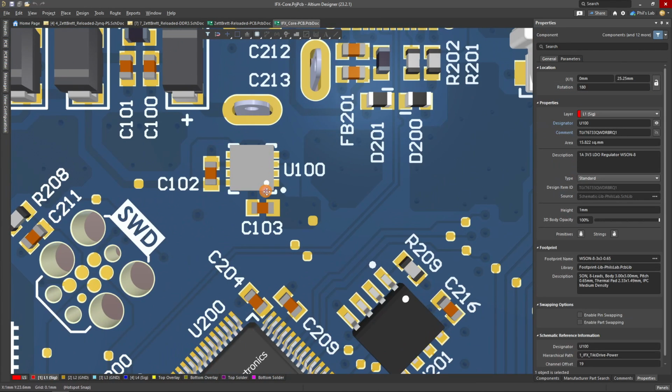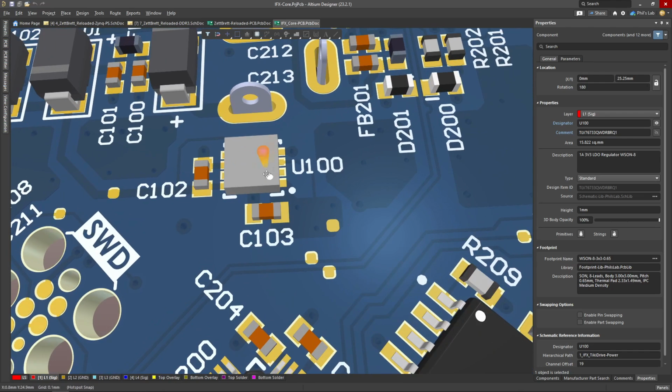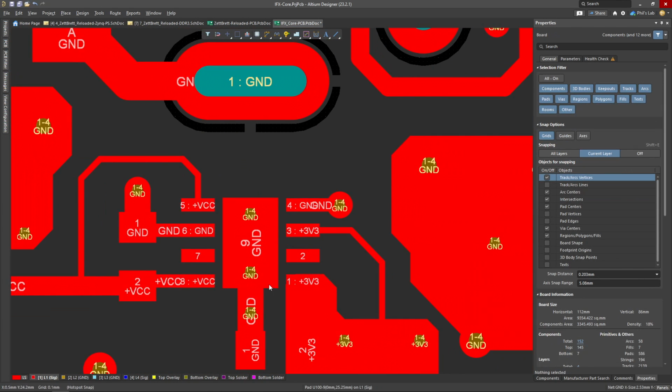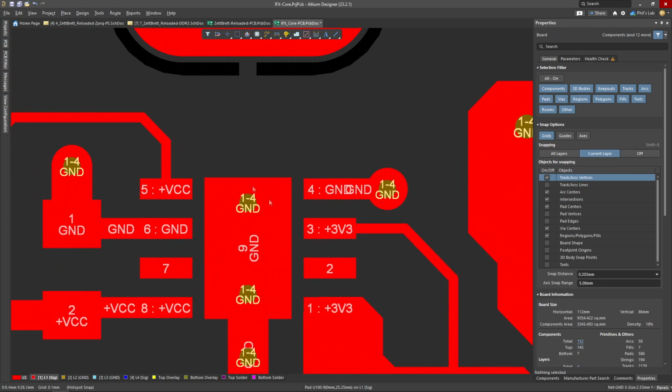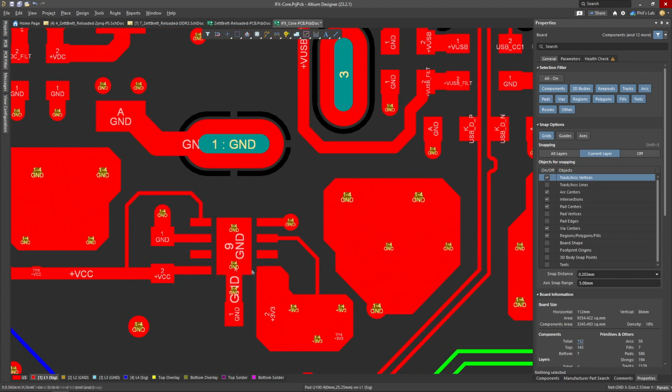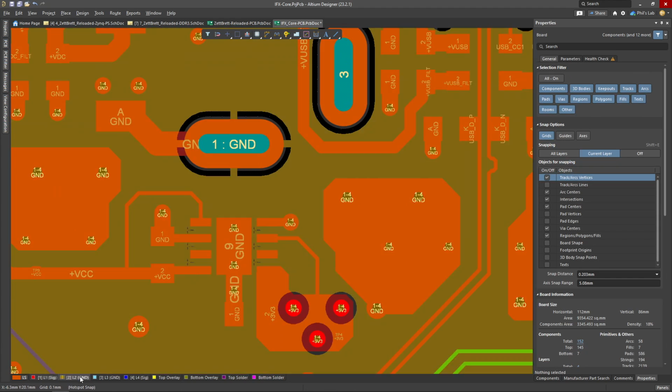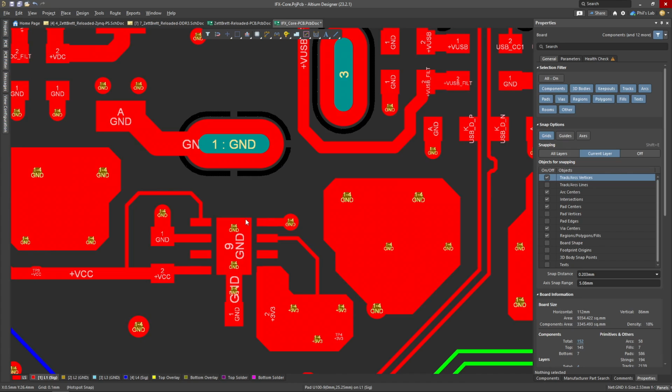This particular regulator is a Texas Instruments TLV76733. It's up to 1 amp nominal output current at 3.3 volts. You can see there's hardly any external parts surrounding this, an input and an output capacitor, and it has an internal voltage reference and generates 3.3 volts at the output without any feedback network. I chose this particular package, again because it has a large exposed thermal pad underneath, to which I can attach vias directly down into internal ground planes and feed away that heat.